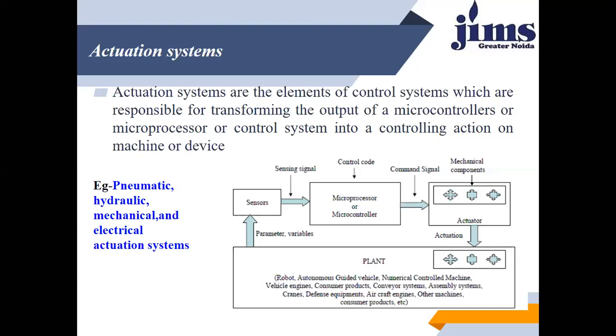So how do you define an actuator? A hydraulic actuator means an actuator wherein hydraulic energy is used to impart the motion. If air is used to impart the motion, that is the pneumatic actuator. A system where energy is imparted to oil, and the hydraulic energy so imparted to the oil is converted into mechanical energy, is what we call the hydraulic system.